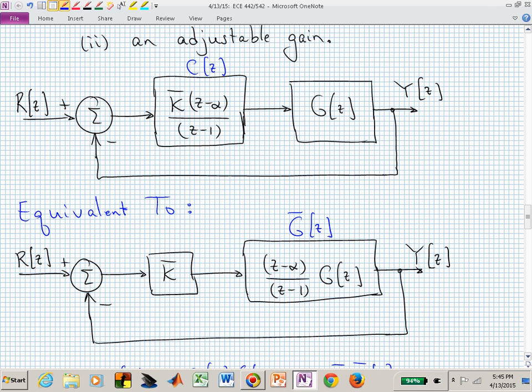That's part of exam 3, but I hope it's clear that if I give you a P controller or a PI controller, you can generate the root locus for either of those two scenarios. And eventually, you're going to learn how to select alpha based on your expertise in the root locus diagram. You'll start to become more comfortable with, if I just put a 0 there, then my branches of the root locus would behave like I want them to.